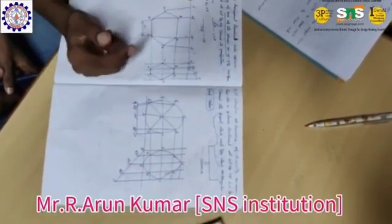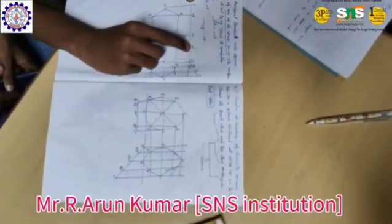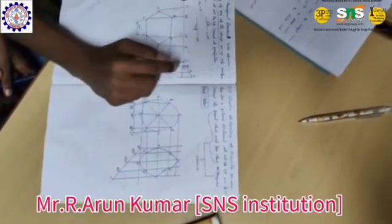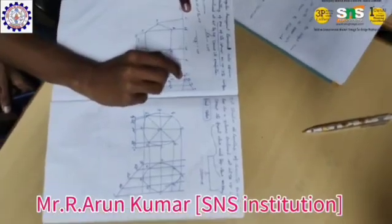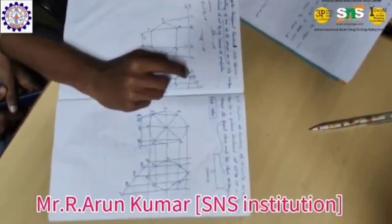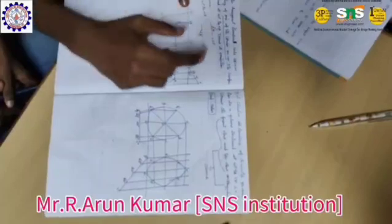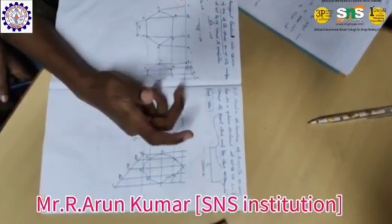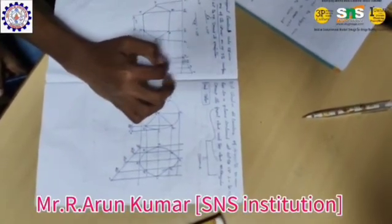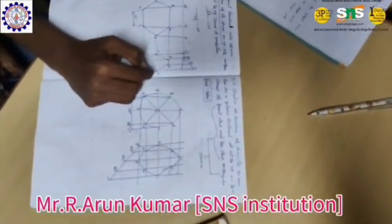Then using a ruler I measure the distance from A dash to B dash in millimeters, and then I place this with the projector and take a 45 degree line, and the same distance is drawn in the place. Here also there is a horizontal position line and a vertical position line, and the other points A, B, C, D are marked.